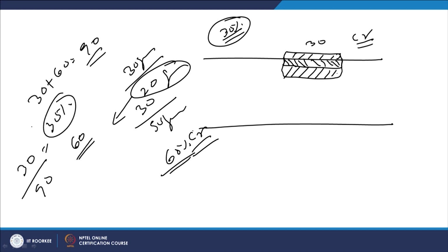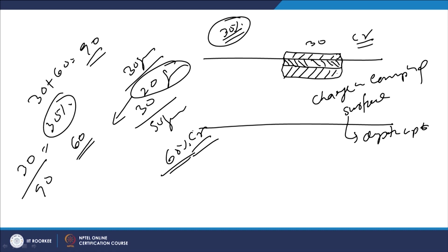So, there will be a significant change with regard to the depth up to which melting of the base metal is taking place. This change in composition of the surface layer is influenced by the depth up to which the substrate is melting.